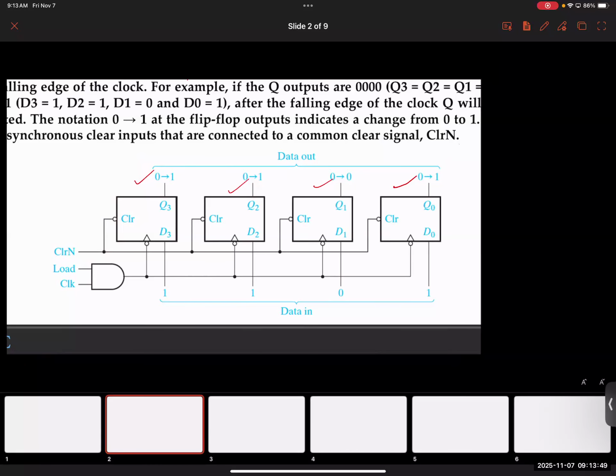How do you know it's a D flip-flop? Basically, we use D as a node name to represent it as a D flip-flop. And D flip-flops are simple because it is just going to send the data to the output. Essentially, there is no toggle, set, reset, JK, or other complicated stuff. Just send the data to the output when the clock edge appears.